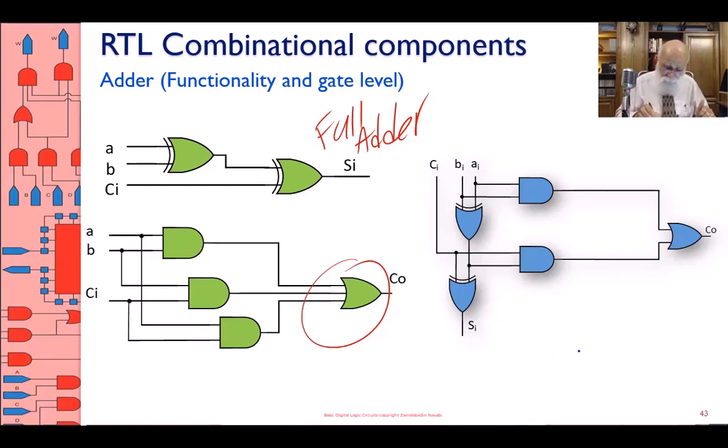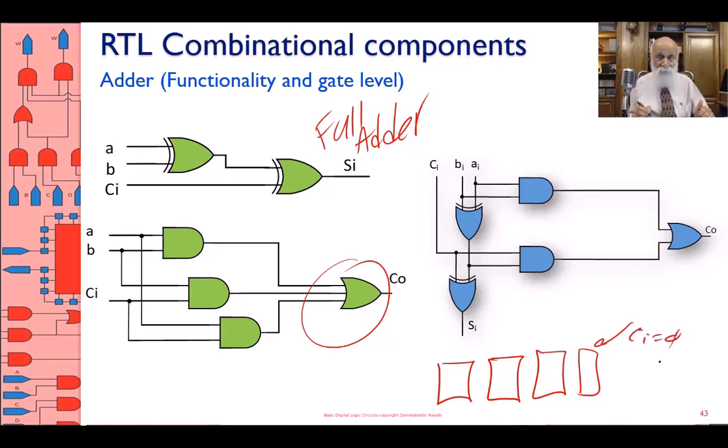Remember that when I was doing my adding, I said that I start with a carry in of 0. If the carry in is always 0, I can always remove the carry in and not include it there at all. Look at this circuit here. If I remove the carry in, I'm going to do it using, let's say, red here.